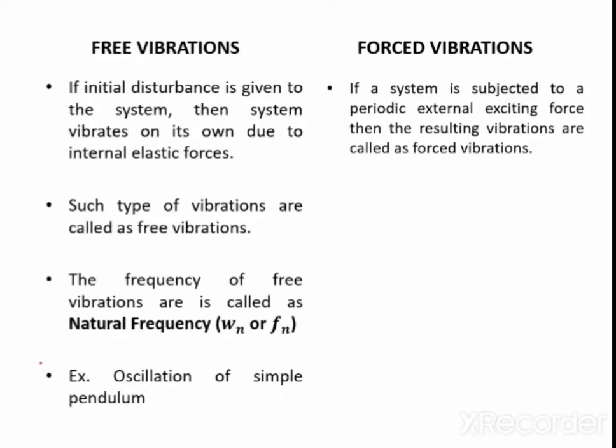Once you start the engine, unless and until you stop the engine, the force from the engine, which is also called the external exciting force, is continuously applied on the system. From the engine, the vibration will be transferred to the chassis. From the chassis, it will go to the wheels, or towards the whole vehicle body. The vibrations are transmitted from the IC engine to the whole vehicle body, right? So unless and until your engine is stopped, you are applying a continuous force.